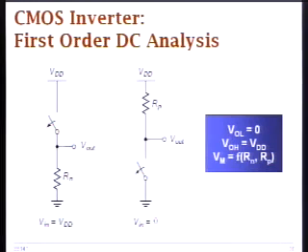So now this is a first order model of this inverter. So it's basically a very simple switch model. Over here on the left hand side, you assume that when your input is equal to logic 1, that is VDD, then your PMOS is turned off. And then you simply have this low resistive path to ground through the equivalent resistance of NMOS.